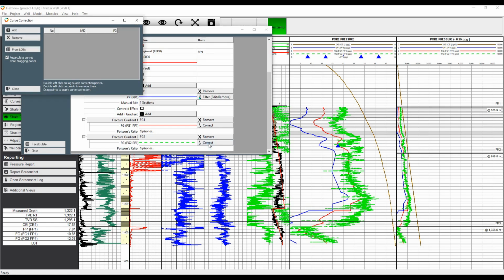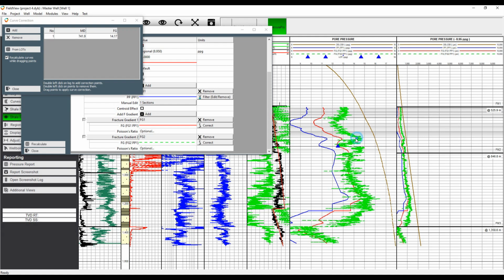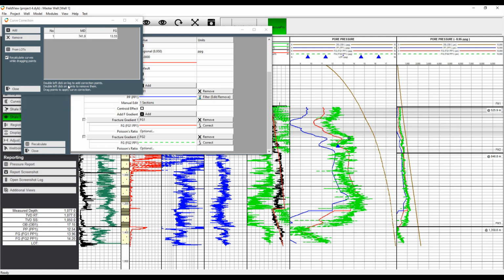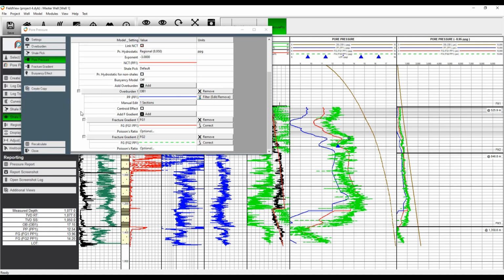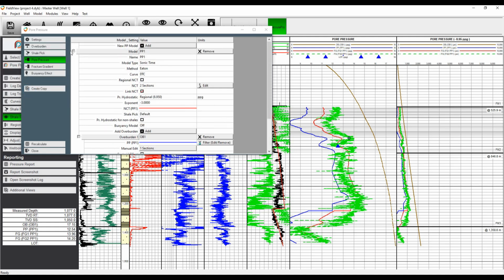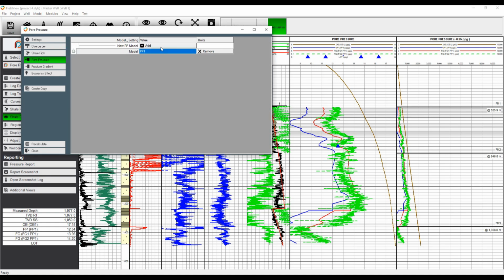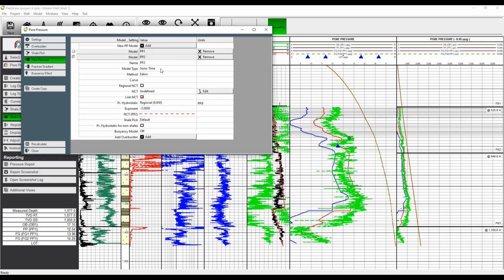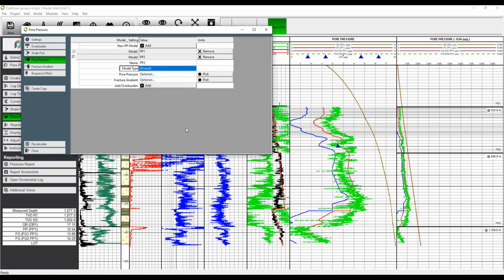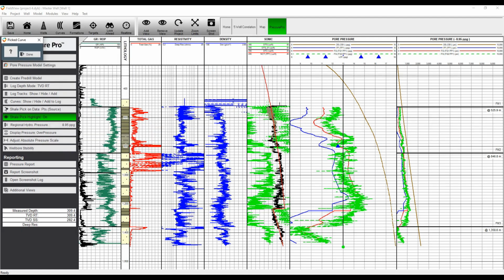In situations where multiple models are being run for multiple sources, such as resistivity, sonic and d-exponent models, the pore pressure and fracture gradient curves will differ. If wanting to interpret an actual pore pressure and fracture gradient from the various curves to provide a single interpretation, we can add a picked model. Add a new model and select the picked option in the model type.